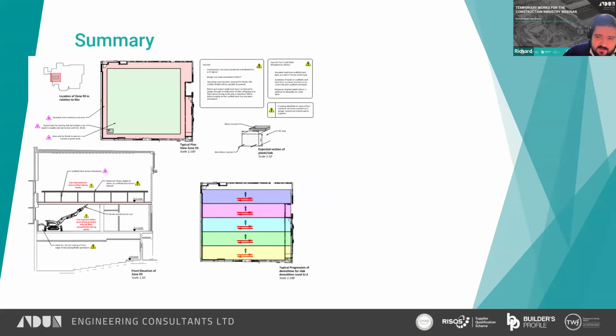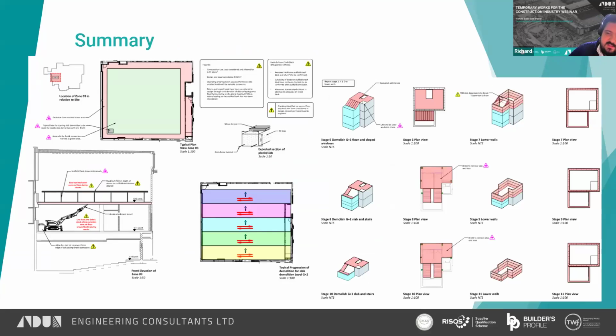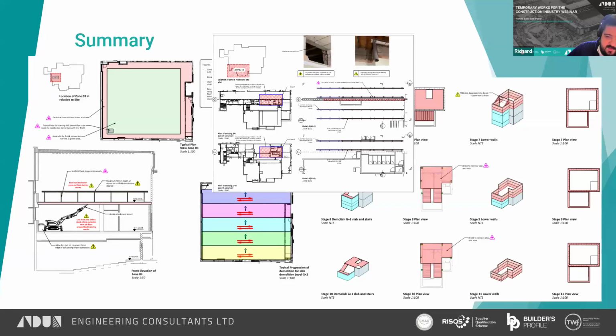And I think all over, what we did at Mould was very useful, and because we had such early engagement, we could help them with a lot of things. So we could do demolition sequences for them, and we could get all the propping. There were plant assessments that needed done, and again, the best propping is no propping when you can get plant to work on floor levels themselves. But sometimes propping is needed, and so we have lines of props where they're needed to remove walls. And in other areas, we created openings in the walls and had more propping there.